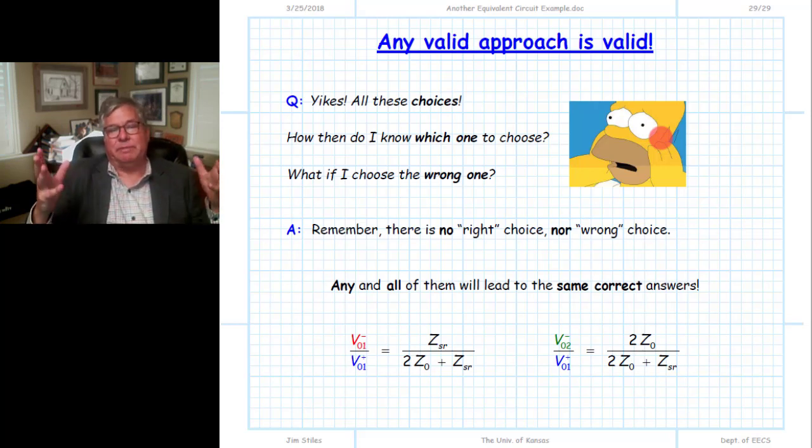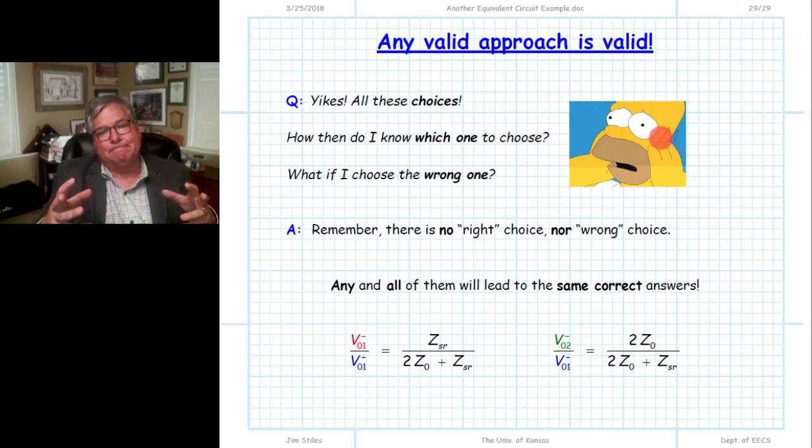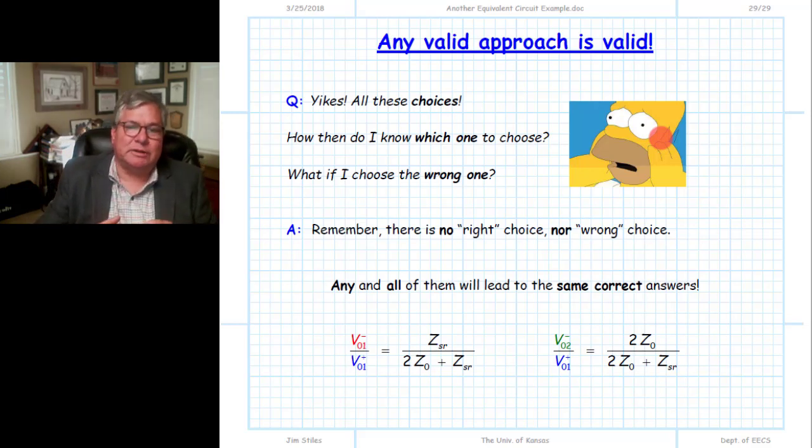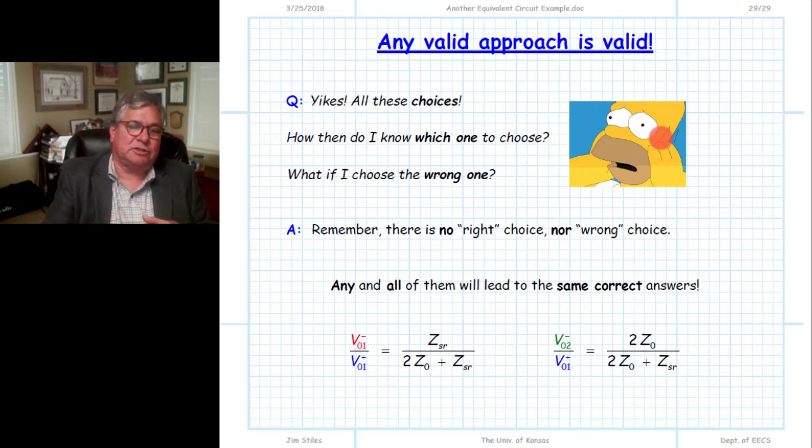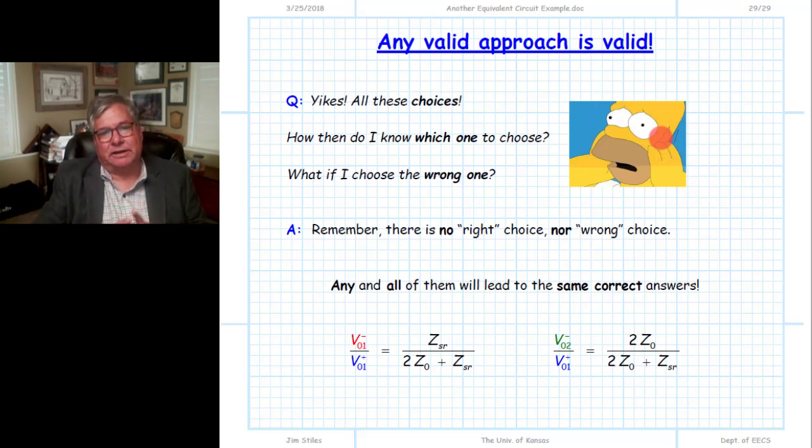You can just make it into a big algebra problem with boundary conditions and multiple equations and multiple unknowns. Oftentimes students will end up getting that answer wrong because there's just too much math to carry around and rewrite. So again, I recommend that when you can, you use this idea of an accordion, the idea of an equivalent circuit. Try to crush the circuit down into as simple a circuit as you possibly can, analyze that part of the circuit, and then propagate the answer from one part to the next, moving up the circuit as you expand and finally getting the complete answer.